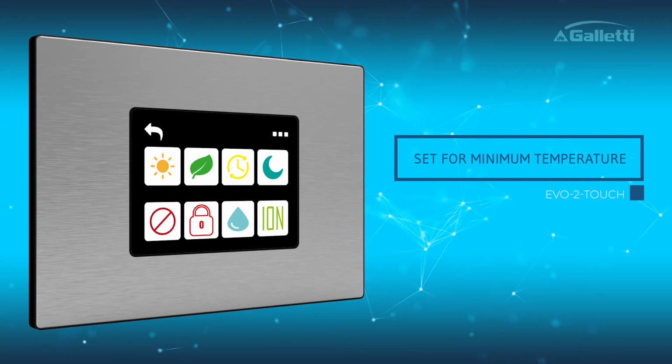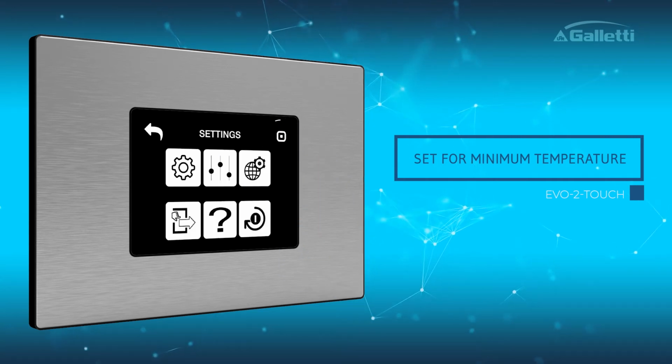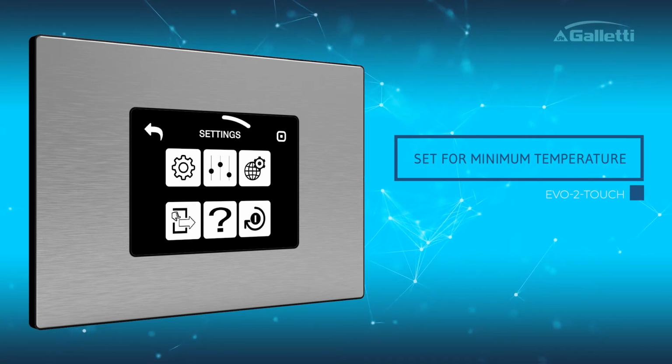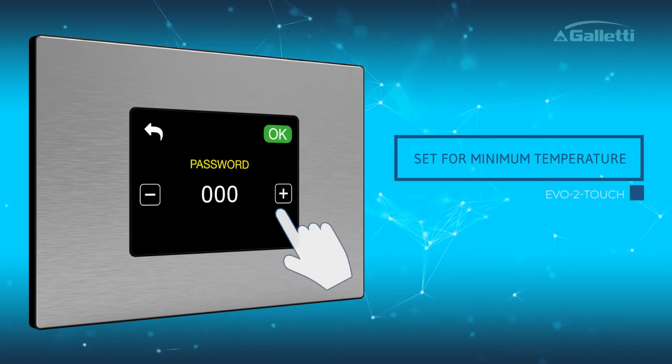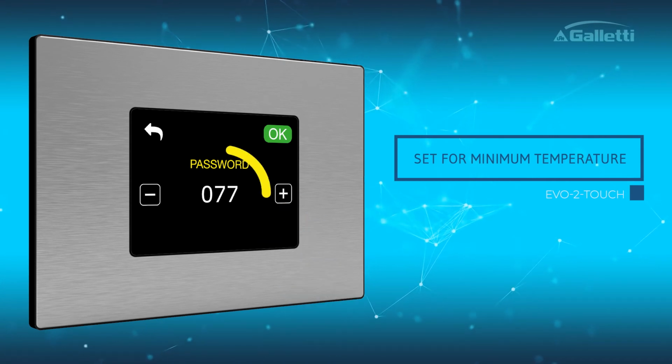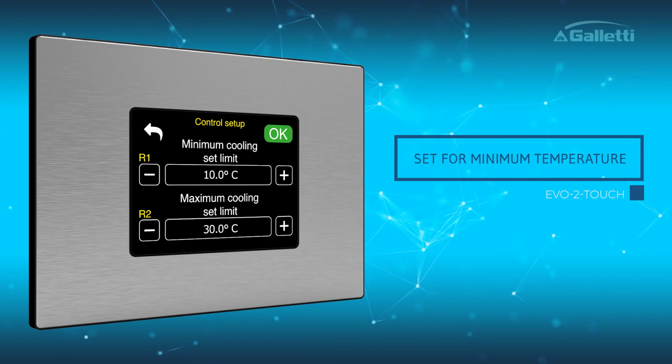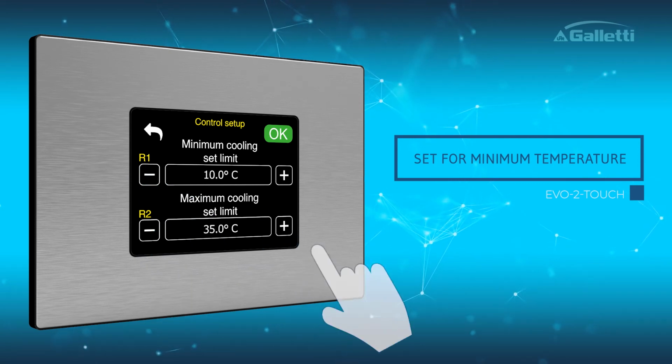From the main menu, click on the 3 dots in the top right-hand corner. To access the settings, click on the second icon from the left and enter the password, in this case, 77. On this screen, you can configure the limit values for the cooling and heating temperature set points.